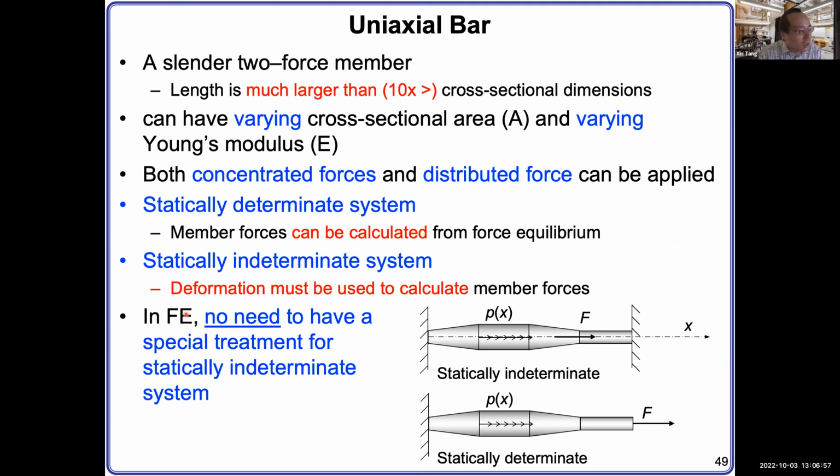because of the nature of how we solve the problem, which is we discretize the system into small pieces, and then for each piece we use the constitutive relationship, Hooke's law, to write the matrix that connects the material deformation, the displacement, with the force applied to the node, which is the external loading. Because we use this way in finite element to solve the problem, in fact there is no need to have a special treatment for those statically indeterminate systems. We don't need to additionally solve the material deformation in the context of external force. We just need to follow the finite element method step by step to solve it.